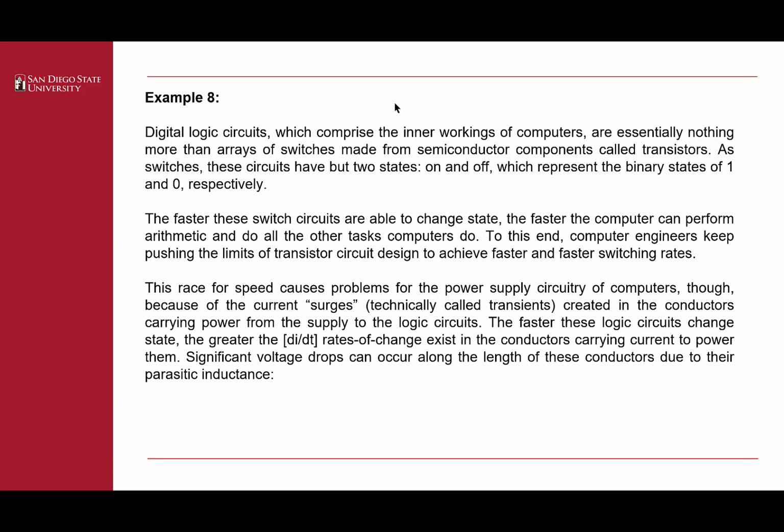To this end, computer engineers keep pushing the limits of transistor circuit design to achieve faster and faster switching rates. This race for speed causes problems also for the power supply circuitry of computers, though, because of the current surges, technically called transients, created in the conductors carrying power from the supply to the logic circuits. The faster these logic circuits change state, the greater the di/dt rates of change exist in the conductors carrying current to power them.